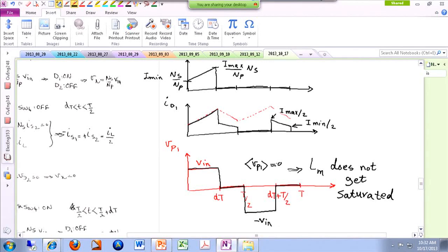And one is 50 turns, and the other is 49.5 turns, something like that. In practice, the push-pull converter has these problems: if you don't do things exactly symmetrically, you are actually forcing your magnetizing inductance to get saturated. There are lots of papers and solutions to avoid that. So just remember, if you build a push-pull converter, the first try that you make is definitely going to saturate and not work. But if you apply some of those tricks, you can make sure that things are symmetric and you're not really violating anything.